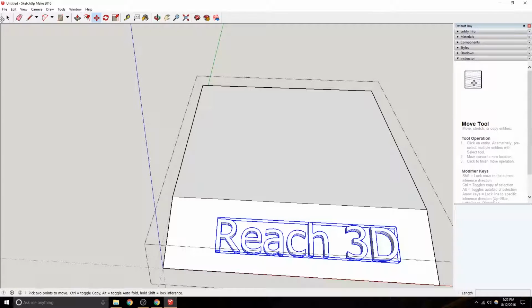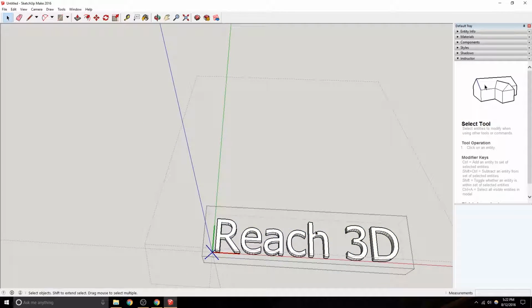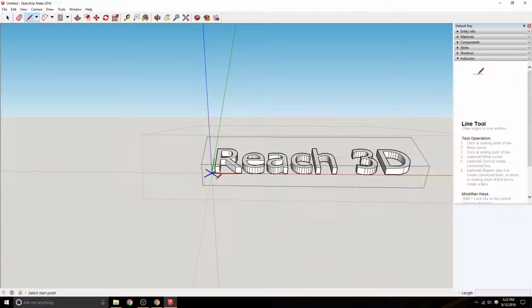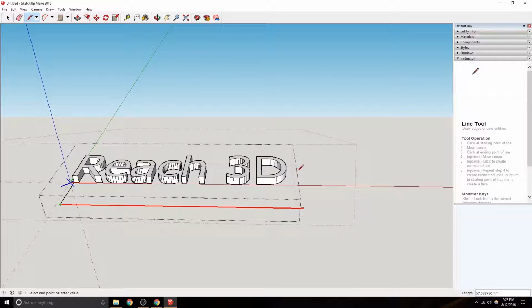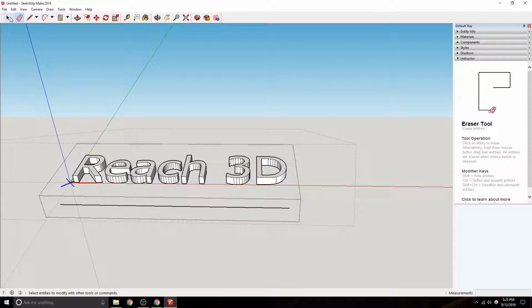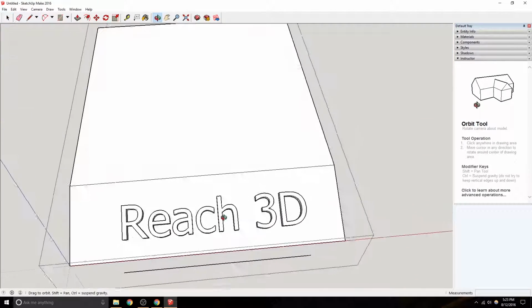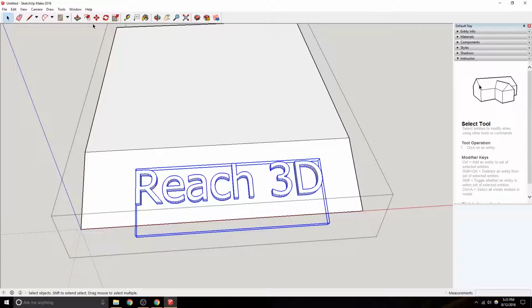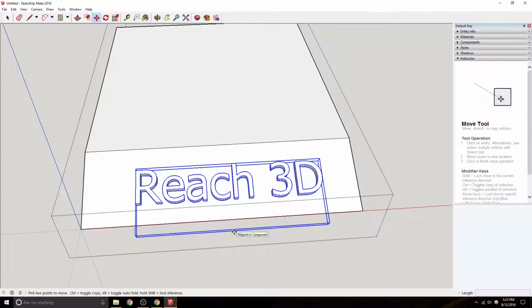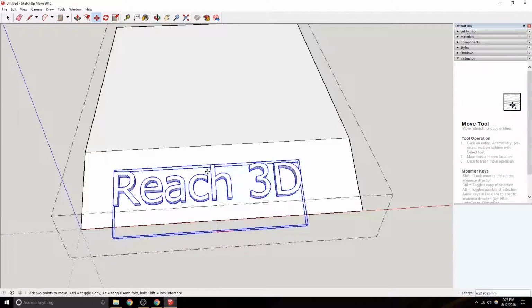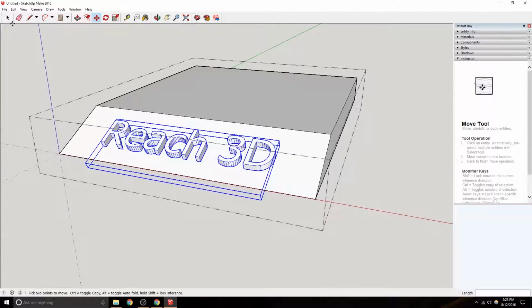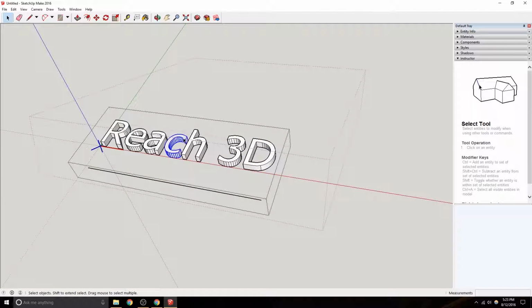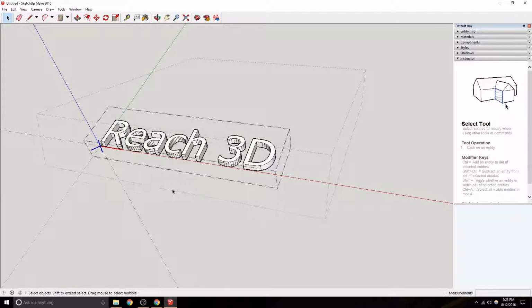Unfortunately, SketchUp has some limitations, like it doesn't give you a grabbing point for the total width of this thing. There are quick ways to grab that however you want to. So I added a line down there so I can center this. Should snap to midpoint. There you go. This takes a second or two. Alright. Back into it. Let's get rid of that line.